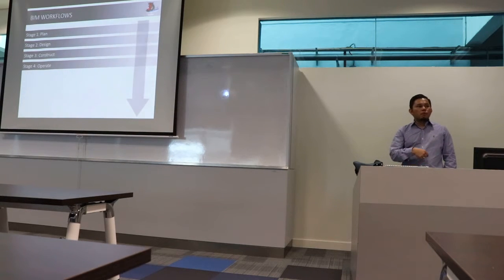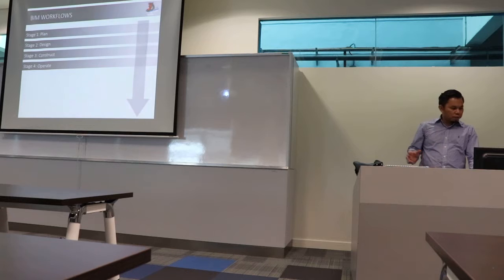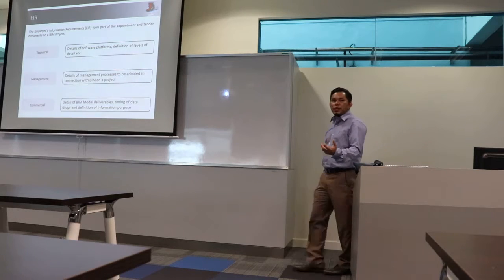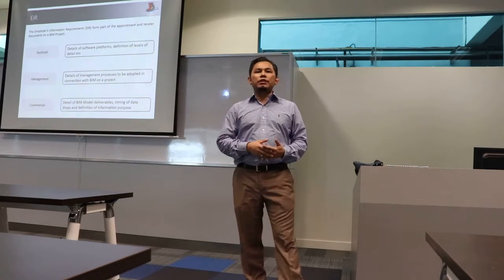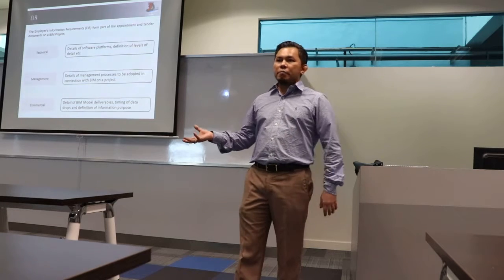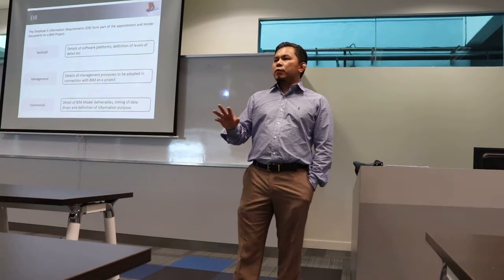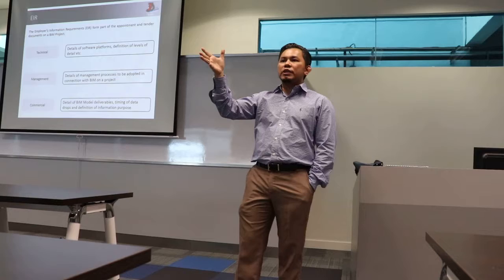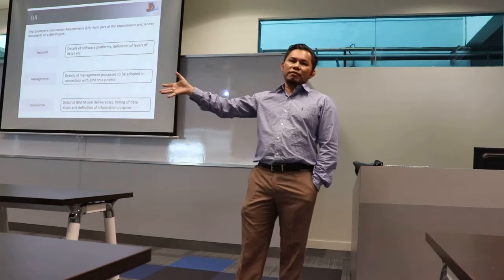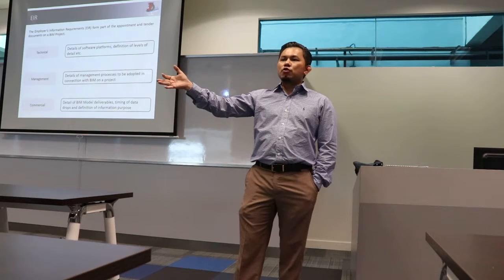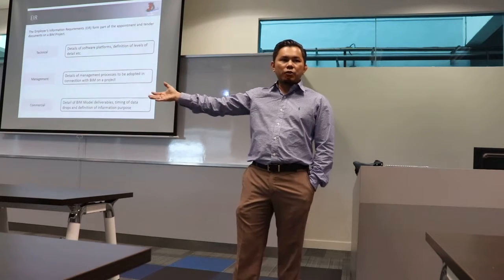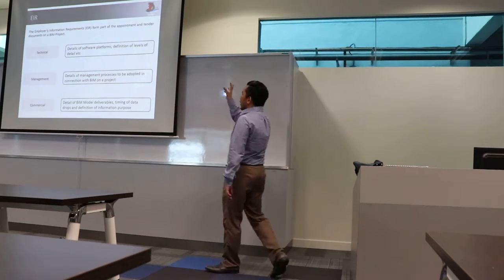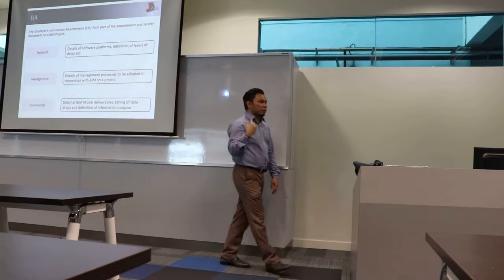So in the workflow for BIM, we can look at it from plan, design, construct, and operate. What is important for any BIM project is for the project owner to come out with the EIR, Employer Information Requirement. When you learn about BIM, one of the things you might have heard a lot is this thing called the BIM PEP, Project Execution Plan. The project execution plan for any BIM-based project processes must be based on the EIR. The EIR comes from the project owner.